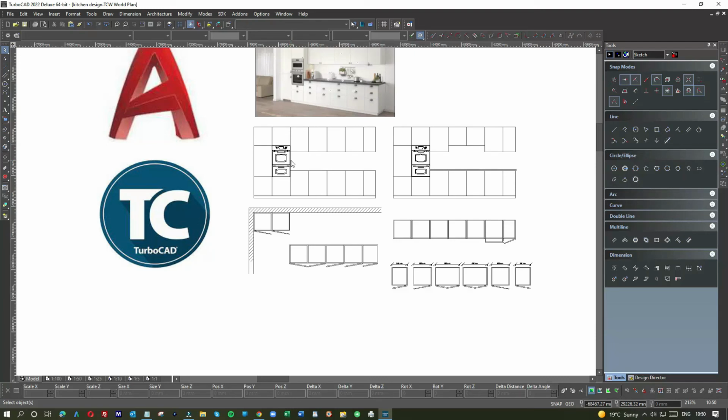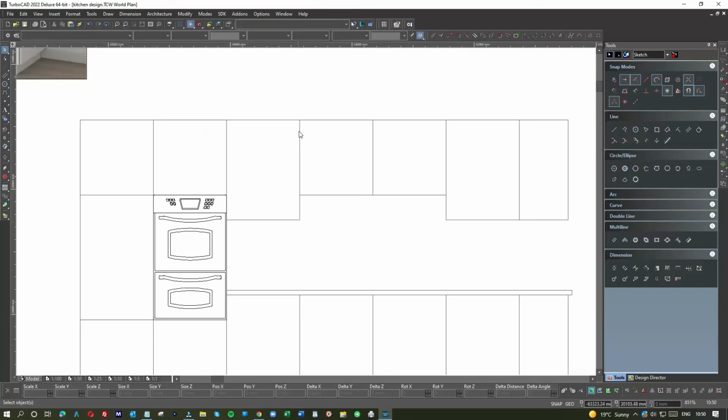So we always use side panels, and I'll show you. Say for example, a side panel would be needed here and here because you've exposed the side of these wall units. So if you have a short unit, you always have to factor in a 12mm side panel, both sides, so everything shuffles down. The problem with that, sometimes it can be a pain, is that if you don't have anything down, you have a choice.